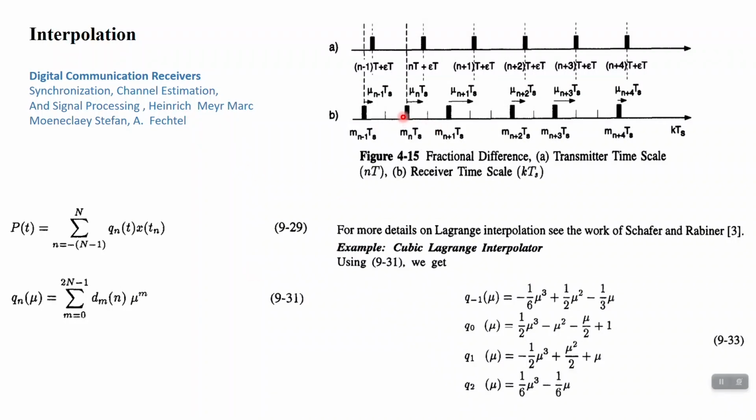uses input samples. This is the input sample in the receiver. Use the input sample, somehow the timing error is corrected on it, as shown here. For example, at this time, the controller tricked the interpolator and commanded it to use the sample at time m_k T_s and the previous sample of it, and use them for interpolation to interpolate a new sample which is shifted by mu_k T_s.